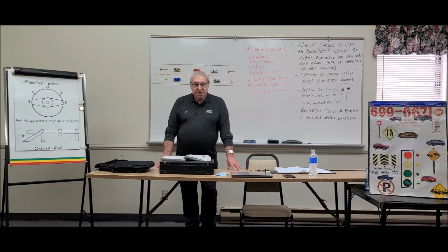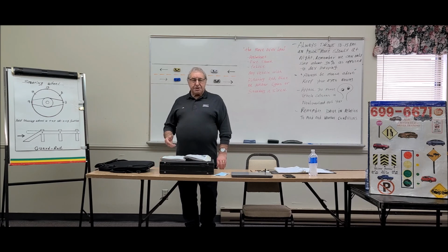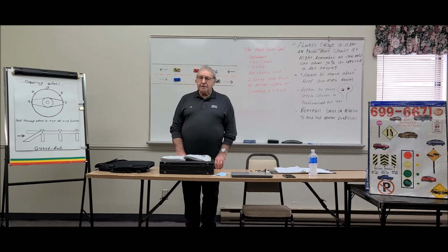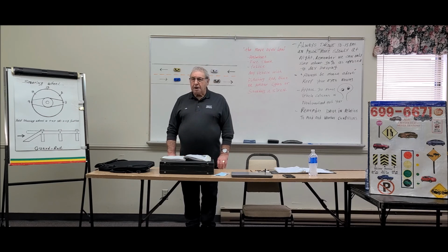Passenger airbag switch. Older cars had the feature whereby you could turn off the passenger airbag if there was no passenger in. But the thing about it, if you picked up a passenger, you may forget to turn on their airbag switch again, and God forbid if they were involved in a collision, their airbag wouldn't operate.